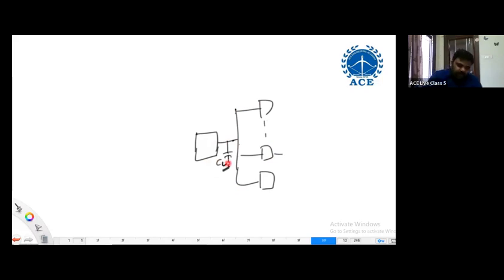When CL increases, the propagation delay of this logic gate is calculated with the input transition time and output load capacitance. Whatever the lookup table mentions for a logic gate, this CL must be within the characterized limits. Then only the propagation delay we calculate with interpolation will be correct.